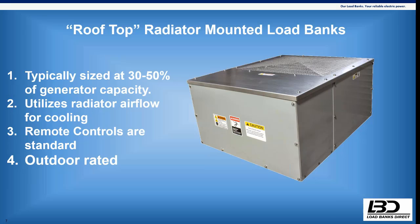Now, some data centers or municipalities, or consulting engineers, might have a requirement to say, look, that 2 meg genset, we need to test it 30 minutes or 1 hour every month at 100% load. Then the stationary application is much better suited.